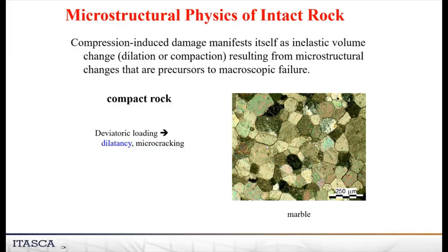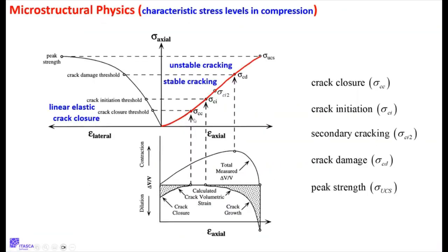But these things start to close when you start to squeeze this. And as soon as they close, there's a new spring. There's new surfaces. There's new stiffness. And so it's the exact same physics. In a granite, you're closing up the initial microstructure, the initial cracks in there.